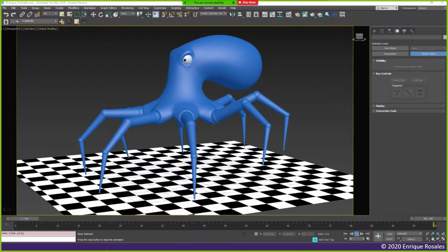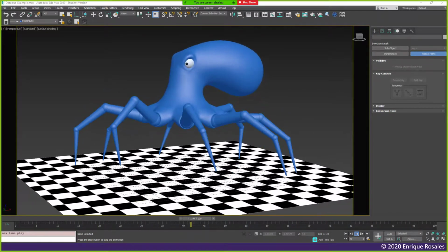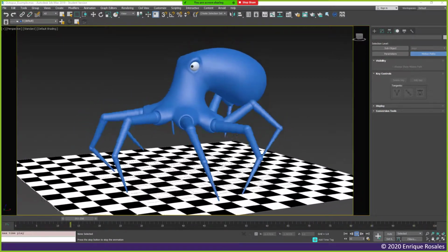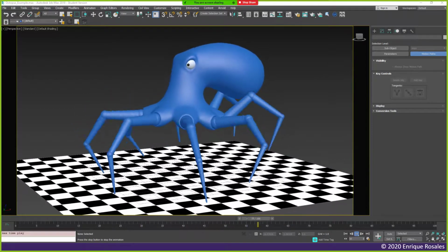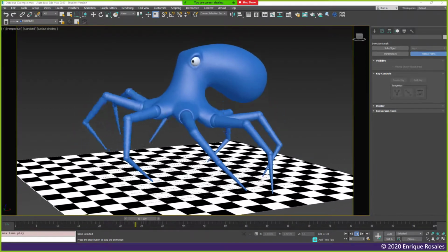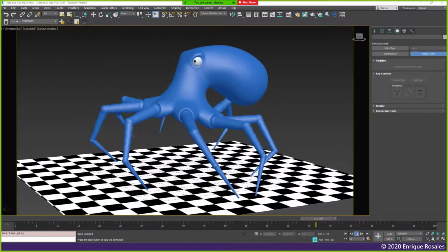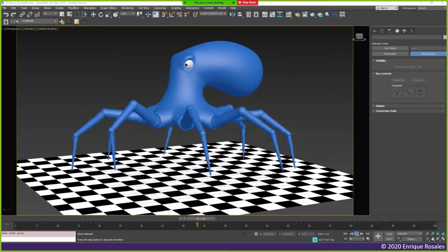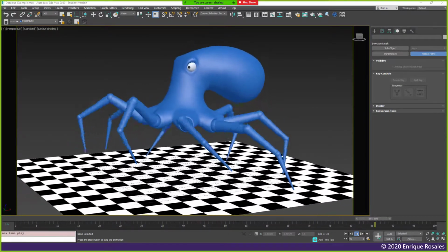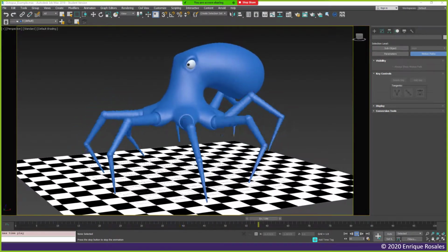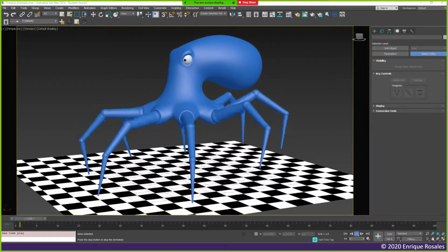If your kinematic chain has only two links, there are only two possible solutions, because two circles will intersect in two points, and those possible solutions are literally the intersection of those two circles. So there's no need for any optimization or anything like that. Usually in robotics, for example, you don't have only two links, you have more links. So if you have more links, of course, there are multiple solutions.